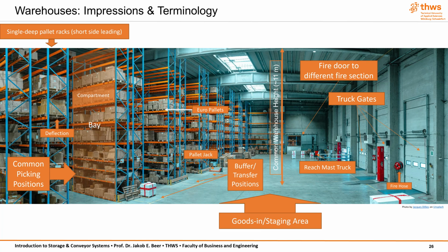Regular inspections, typically conducted as part of facility safety audits, are necessary to ensure that the doors close properly, the seals are intact, and the control systems function as intended. More than once I have found fire doors blocked by pallets left in the way for temporary storage, which should never happen. If a fire door can't close because it's obstructed and the entire warehouse burns down because the fire could not be contained, your fire insurance has very good reason to withhold payment.